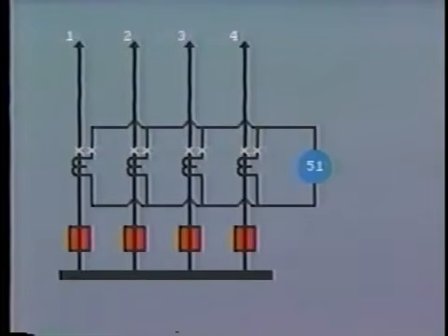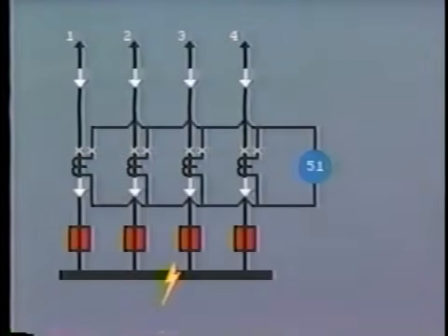This would not be such a problem with operation due to a fault on the bus, because the current in all of the connected circuits now feeding into the bus would be of a similar magnitude. However, in the case of a through fault, this CT unbalance or error current could cause inadvertent operation.